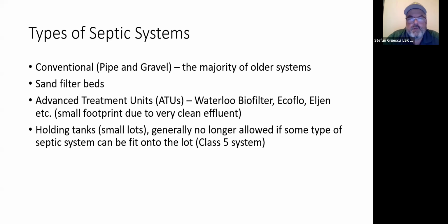So everything from the home accumulates into the tank, and when it's full, we have to go and pump it out. So obviously, they're not highly favorable if you can avoid them. Generally, they're not even allowed under the building code if a septic system can fit on the lot. But that's a real challenge in some of these lots, especially because we have to be certain distances away from water, certain distances away from neighboring wells. So sometimes we just cannot fit a septic, conventional septic or any other kind of thing.